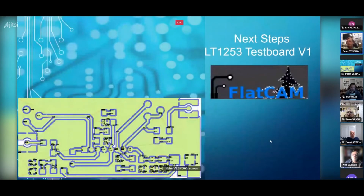So after I get all that work done with the KiCad and am happy with that, I then generate the Gerbers, and I import the Gerber files into a program called FlatCAM. I've got version 1 identified up there, but this is actually the version 2 board, and you can tell that by the output here, the SMA connector up there. And in FlatCAM, what you do is tell the program what kind of milling bit you're using, what depth you want to go into the board, the number of passes you want to make around the traces, and the percentage of overlap on the traces.